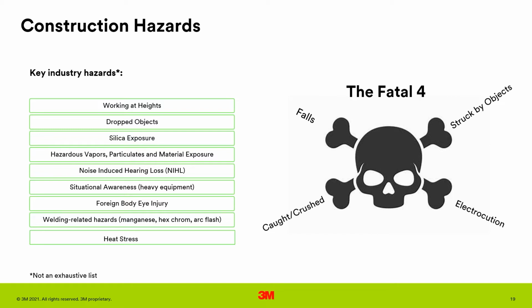There's also this idea that you need to be aware of what's going on around you, because it's not like working in a building, because there's heavy equipment that's moving around you that could potentially injure you and get you caught or crushed in something. You have to worry about eye injuries and also exposures to welding related hazards, including manganese, hex chrome, the flash itself. And also on a construction site, heat stress is a major concern.